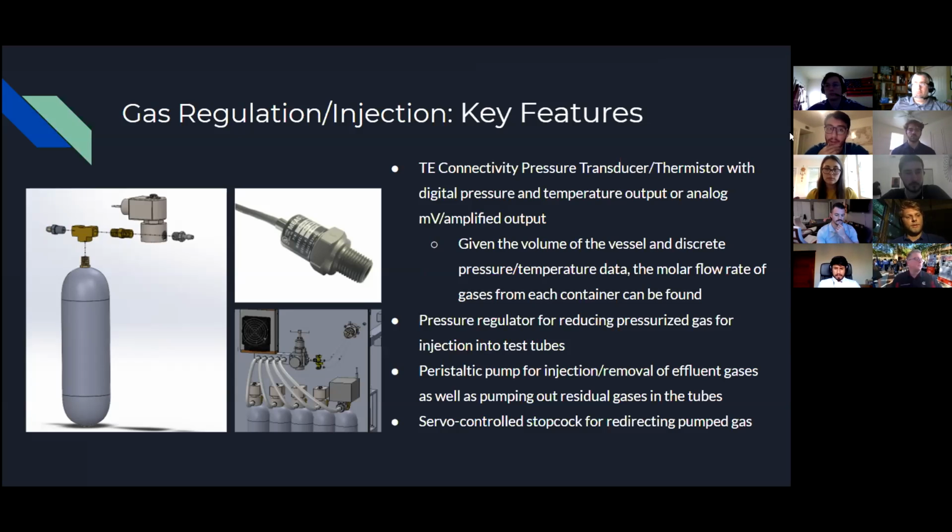And to meet safety requirements, the pressure vessel has a factor of safety of 5 when containing inert gas at 800 psi. And all components are mounted to the outside of the frame, and all pneumatic threads are 1/4 inch, meeting National Pipe Thread standards, allowing the design to be modular and easily assembled. Next slide.